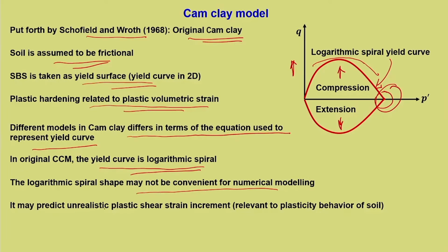So, it may predict unrealistic plastic shear strain increment. Now, again I would like to use this particular word with caution, because we are not discussing the plastic shear strain increment yet. It is basically relevant to the plasticity behavior of soil. So, there is an issue that this particular model can predict unrealistic plastic shear strain increment. So, let us understand what is the mathematical representation of the Cam clay model yield curve.